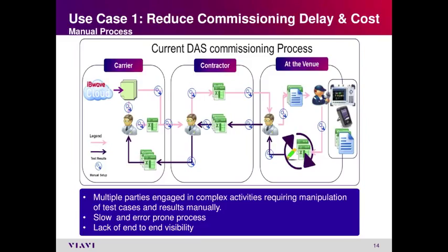It's identified. All that information is then sent to the venue, where a project manager who is managing the whole DAS deployment works with the technician, who is using test gear like a T-Berd for optical testing, a spectrum analyzer, or a sweep test tool like a base station analyzer or a cable and antenna analyzer to analyze the sweeps and perform the OTDR testing. Once all those tests are done, manually, by the way, all these steps are manual, the results are reported back and filled in a spreadsheet. So as you can see, it's a very tedious and error-prone process.